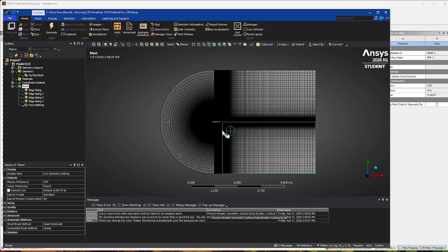So then last thing we're gonna do with the meshing here is we're gonna name our edges that we need. So I'm gonna control click, we're gonna do edge select, you're gonna control click all of this. Nope, not that one. We're gonna do all of this.